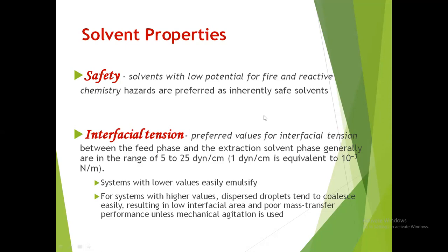In our language, if you allow me to use the vernacular, the droplets coalesce; they should be separate. They stick together. So if they form one lump, if these dispersed droplets won't remain dispersed but rather lump themselves together, then interfacial area is decreased. If interfacial area or surface area is decreased, then of course mass transfer is decreased.